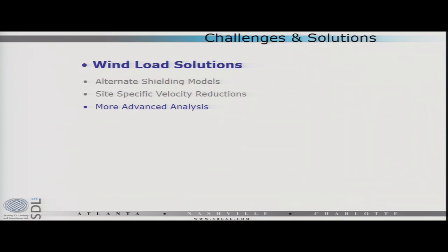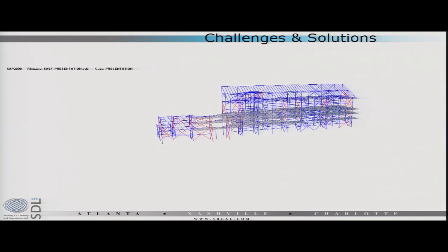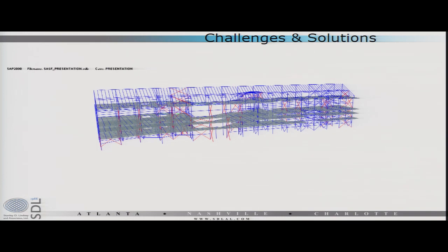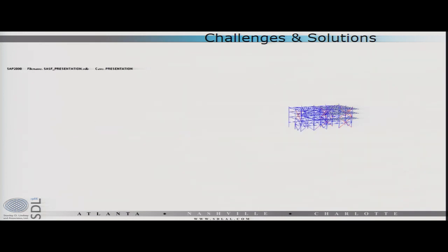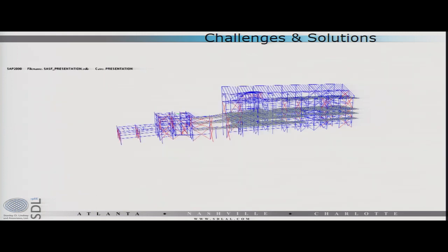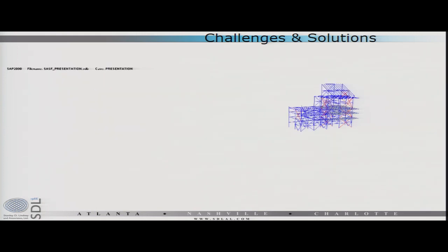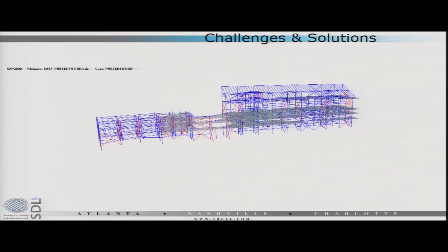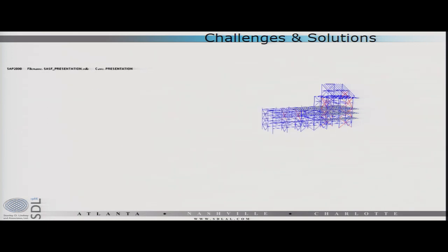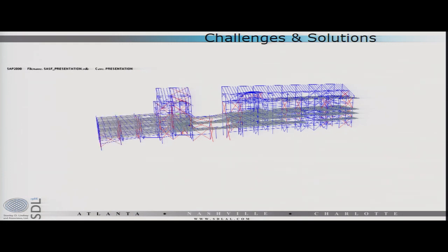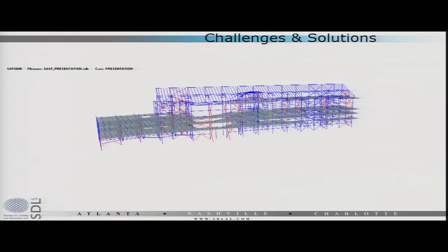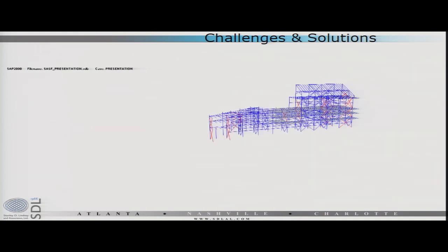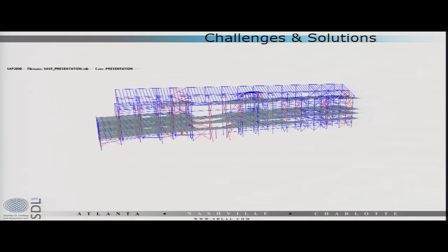Engineers can do engineering stuff and spend more time with analysis. So you're talking about things like staging in the stiffness of the deck and then the stiffness of the concrete, looking at partial restraint of supposedly simple connections, base conditions. All these things can be done. All these things take time. Time takes money. So it's a give and take with how much time and fee is available for you to be able to do these sort of things and the bracing that comes out of them.